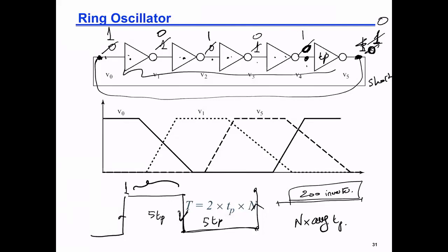Professor, does this change over time? Yes, there is an aging effect on chips that can be translated to delay variation, and this is why also the string oscillators are good monitors. And this is why they put something they call canary cells, meaning like messengers or birds that tell me the activity of the chip and how it is aging and stuff like that. So these are all good indicators for monitoring the chip behavior. Yes. Okay. Thank you, Professor. Okay, thank you very much.